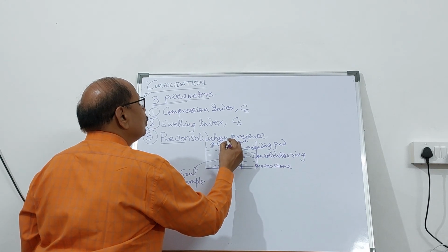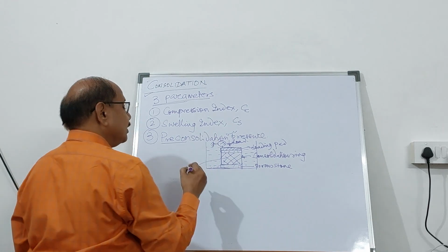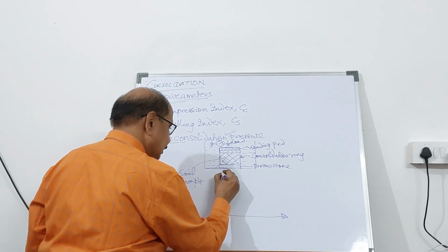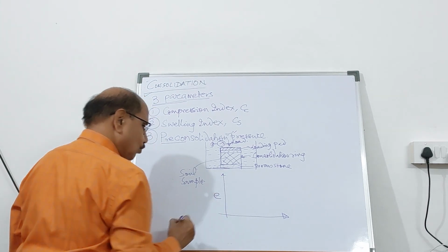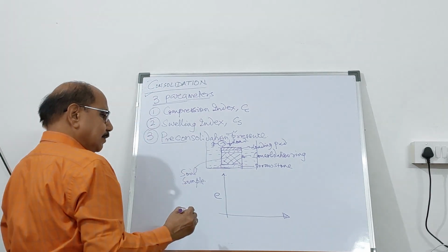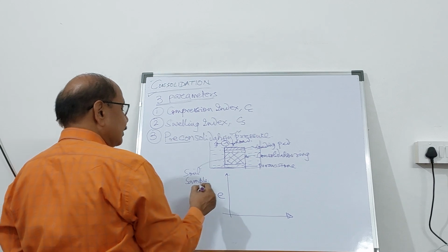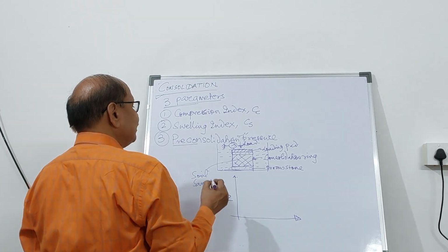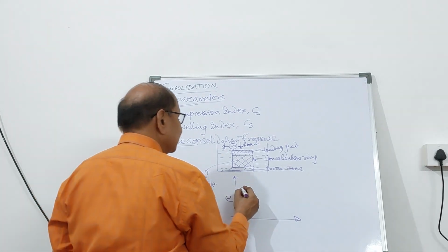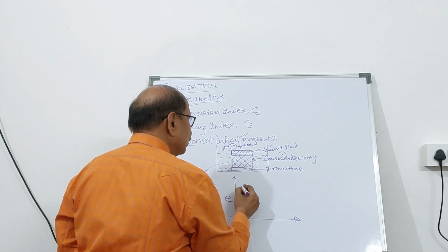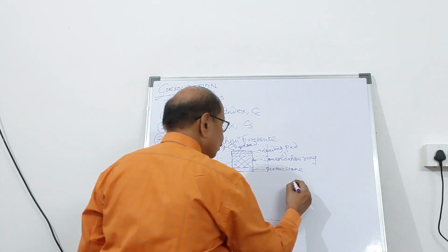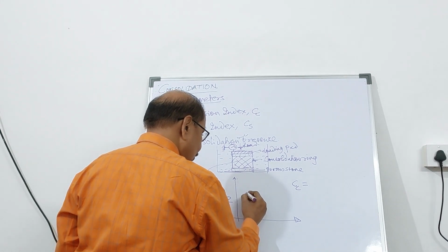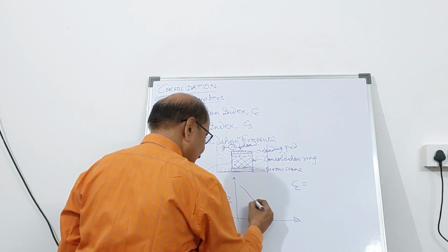So under the given increment of the loading, let's say the increment of the loading sigma prime, you can get the void ratio from the dial reading, and you will be able to get the value of compression index. So compression index can be easily found out by performing the test, and you will be in a position to get the value of the CC. If you plot it, initially the void ratio reduction will take place. So it is going to be like this.